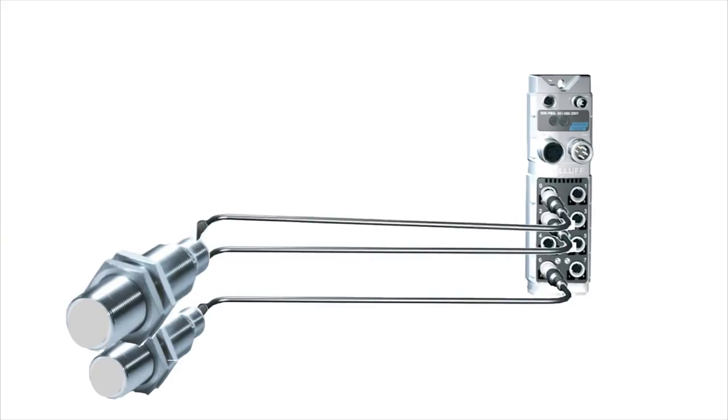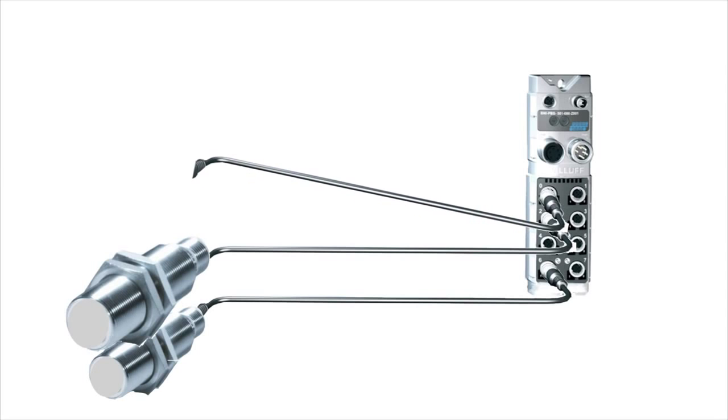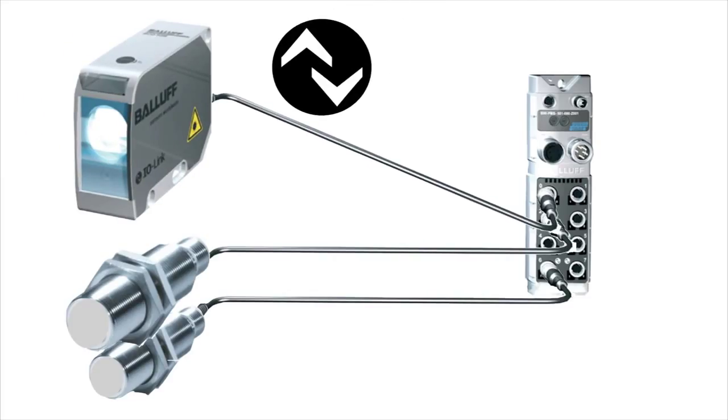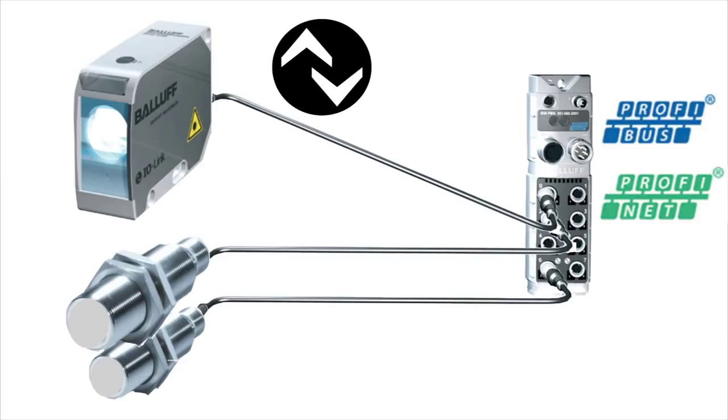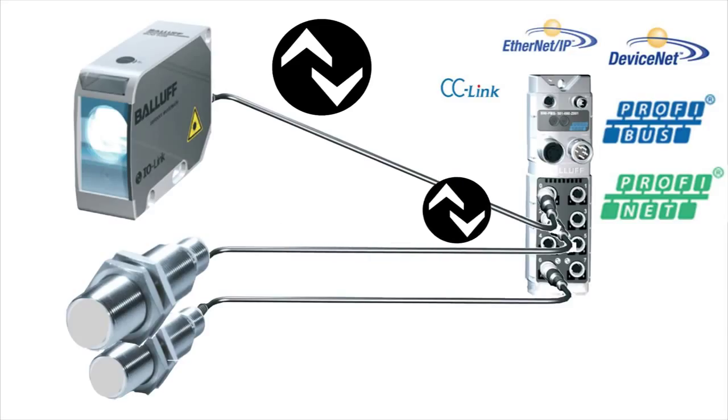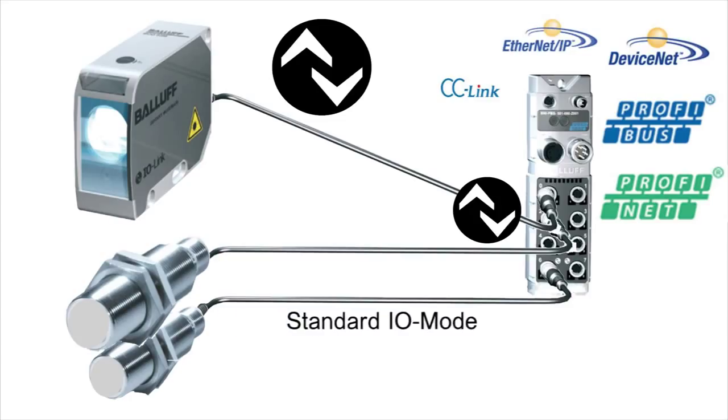IO-Link uses existing communications systems all the way down to the actuators and sensors. And therefore, IO-Link is 100% compatible to existing technology in terms of cabling and utilizes existing field bus communications platform, for example Profibus, Profinet, etc. IO-Link meets the backwards compatibility with standard sensors and actuators. Thus, binary IO-Link sensors and actuators can always be connected to existing I/O modules. Likewise, a sensor which doesn't have communications capabilities can still be connected to an IO-Link I/O module.